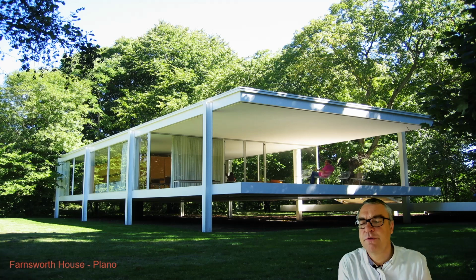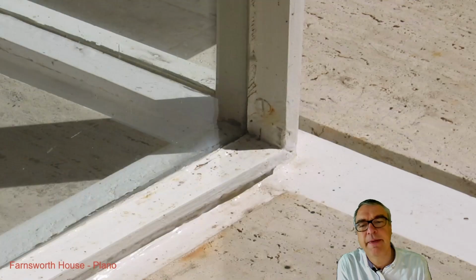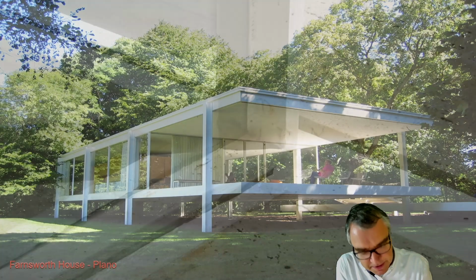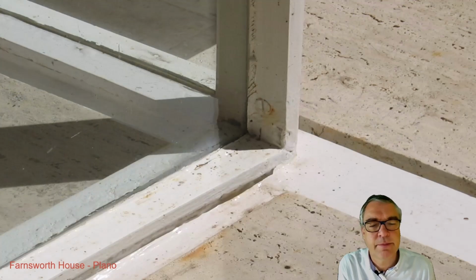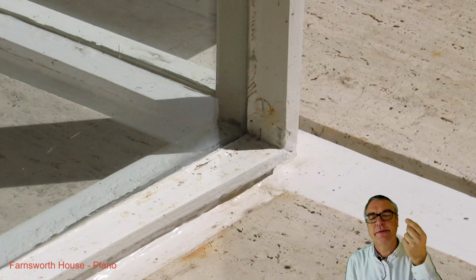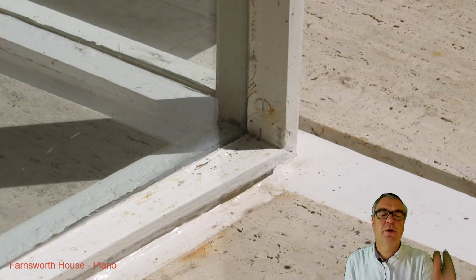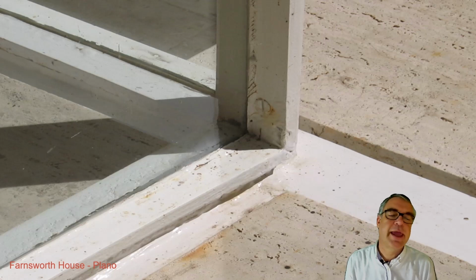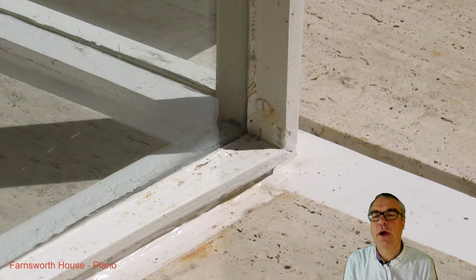Similar is the Farnsworth House from Mies van der Rohe, where when we look at this, we feel like, oh, we are so jealous that they were able to get such slender structures. It's in the north of Chicago, so wintertime is very, very hard. It's a single-layered glass surface with no insulation value, which means it must be super cold inside this building if you're staying in this house in wintertime, which you obviously didn't do because it technically didn't work out well.